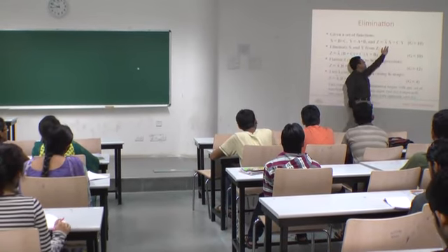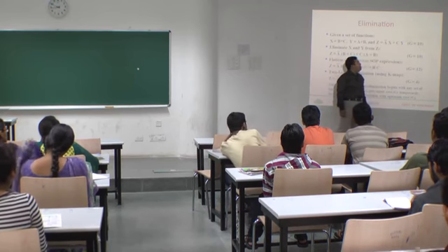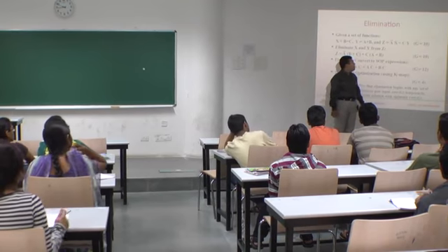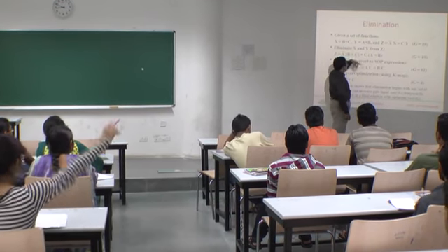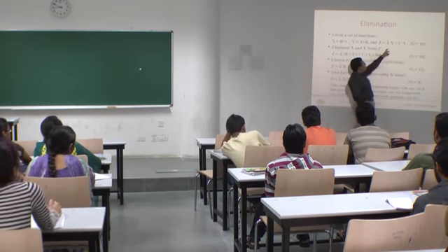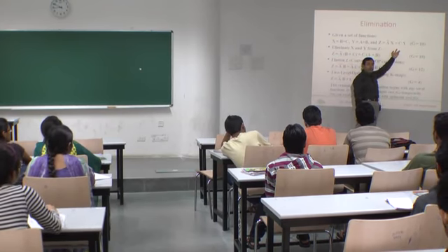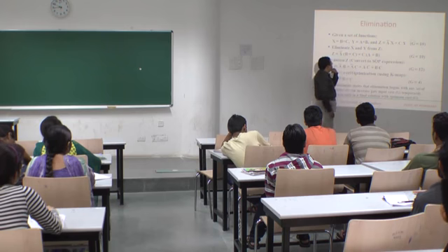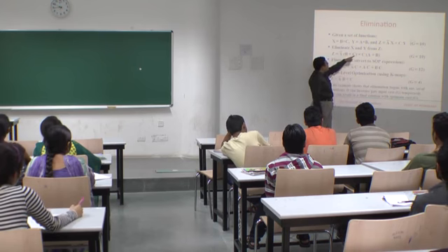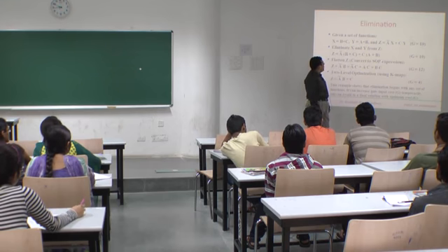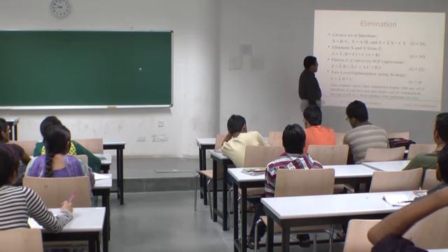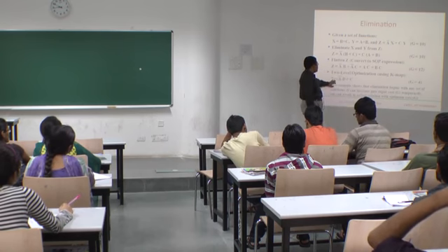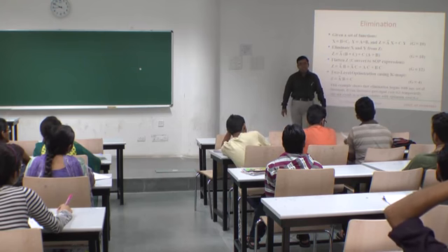For example, over here you can see this z equals a complement x or cy, but these x and y have been computed before. So there is no need to externally provide these inputs x, y. So we will reuse these functions over there. Naturally, if I put b or c for x and a or b for y, then I convert it into an SOP expression, and after minimization it comes down to z equals a complement b or c.